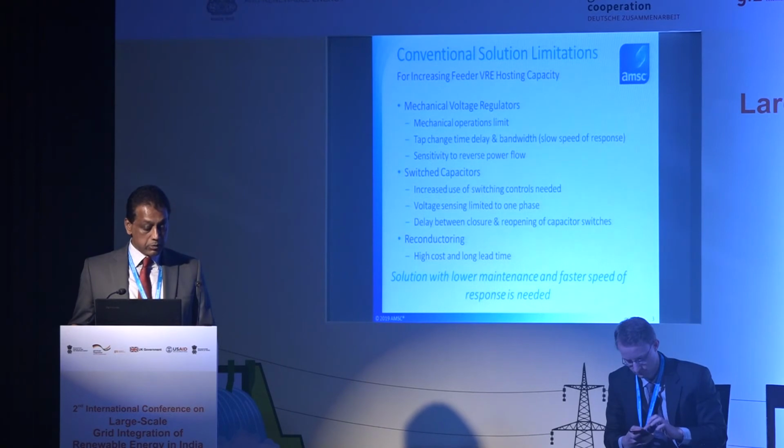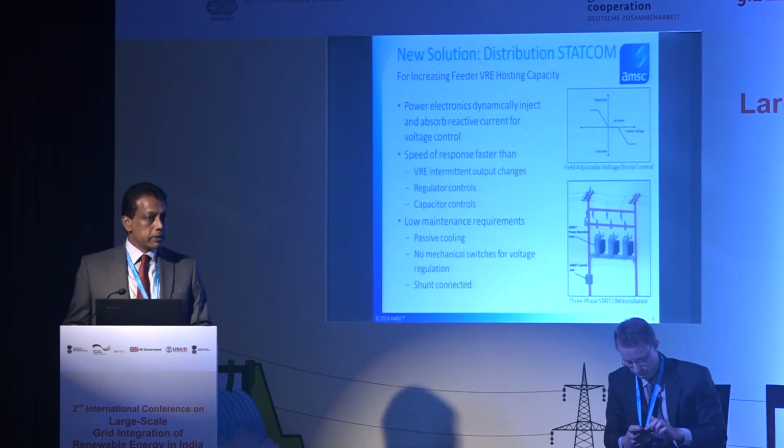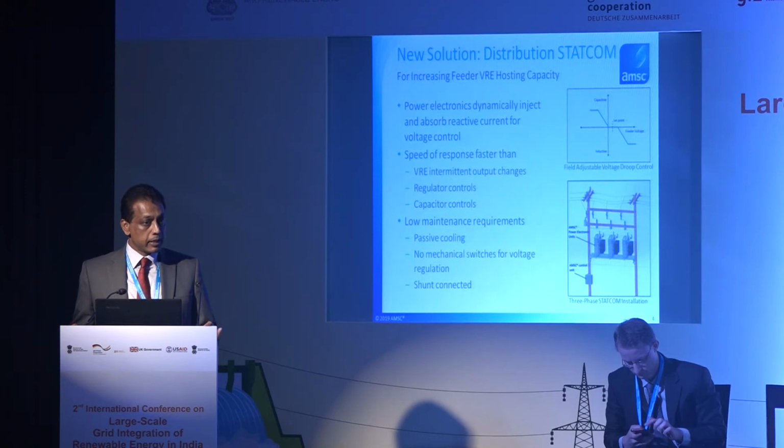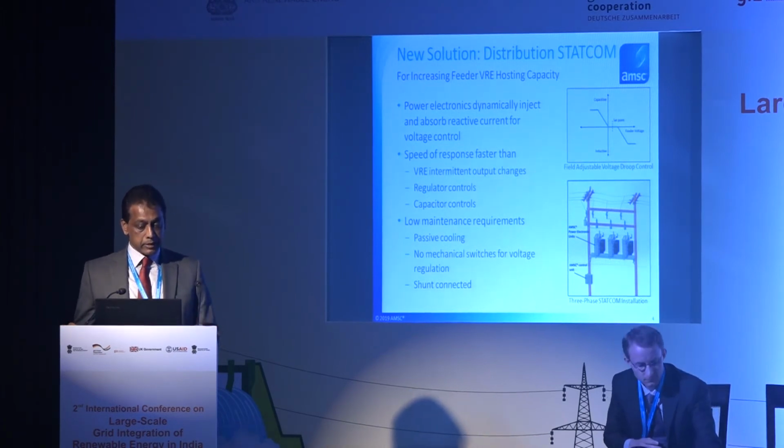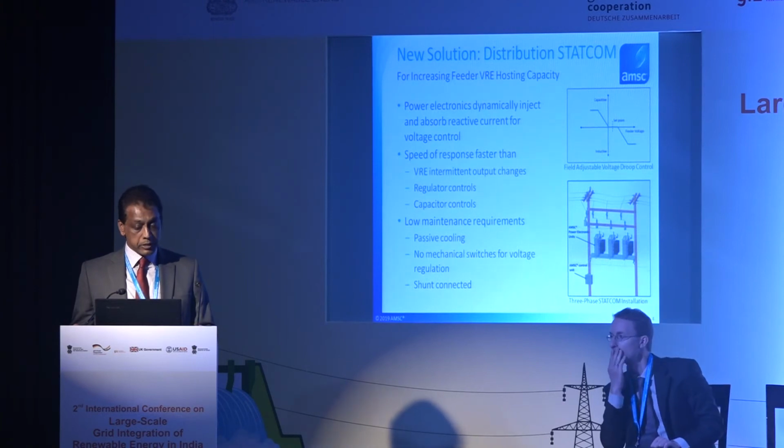The solution is you could reconductor it, but of course that means a pretty high cost and long lead times to do that. So what we've been looking at, AMSC has been in the business of reactive compensation systems since the early 2000s, and we've sold over 170 STATCOM systems for various applications, including renewable integration of large wind and solar farms throughout the world. So as part of making the STATCOM system, which is our D-VAR STATCOMs for the large systems, we started